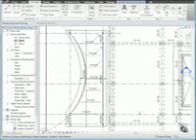Click OK. Then, under Annotation Location and Type, on the Level Beams in Plan tab, click Browse to specify the top end annotation type. In the Select Annotation Type dialog, under Select Element to Place, click Structural Framing Tag and click OK. Then, in the Beam Annotations dialog, click OK.